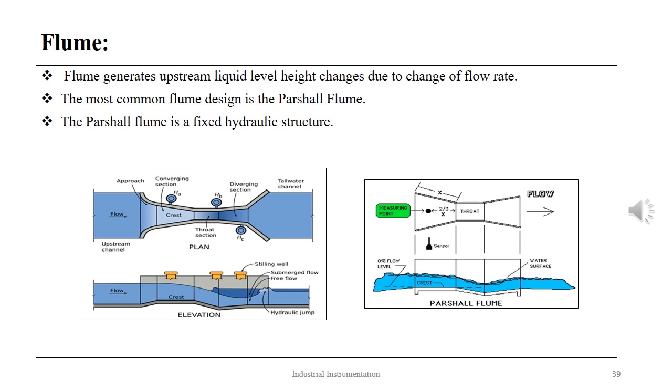Discharge through weirs and flumes is a function of level, so level measurement techniques must be used with the equipment to determine flow rates. Staff gauges and float-operated units are the simplest devices used for this purpose. Various electronic sensing, totalizing and recording systems are also available in flume open channel flow measurement.